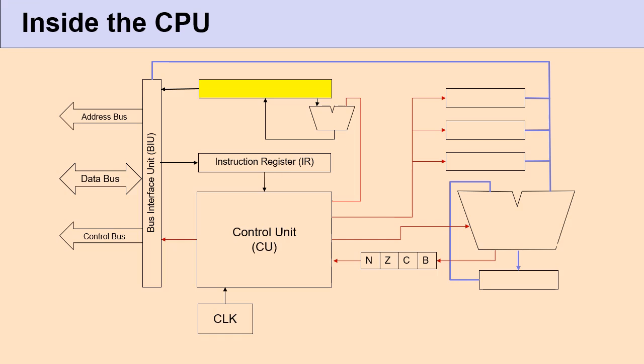In most designs of the CPU, to support this case, a special ALU is provided. Because otherwise, if I do this operation on the regular ALU, it will consume more time. So, to support this addition of the instruction length and updating the program counter on every instruction as part of the instruction fetch itself, most CPUs are provided with a small ALU near the program counter, which is directly connected to the program counter.